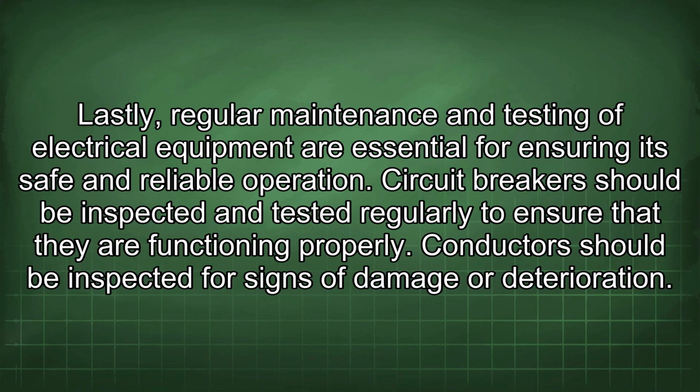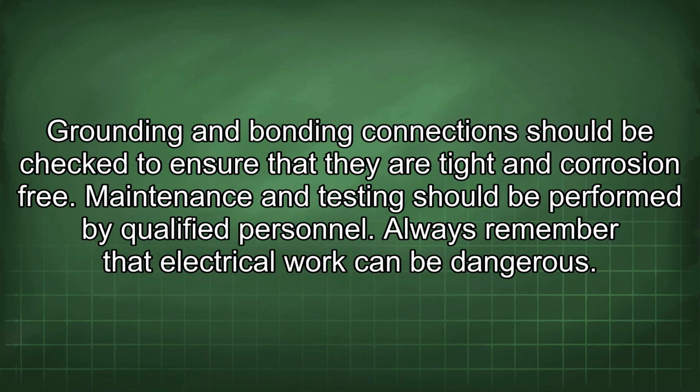Lastly, regular maintenance and testing of electrical equipment are essential for ensuring its safe and reliable operation. Circuit breakers should be inspected and tested regularly to ensure that they are functioning properly. Conductors should be inspected for signs of damage or deterioration. Grounding and bonding connections should be checked to ensure that they are tight and corrosion-free. Maintenance and testing should be performed by qualified personnel.